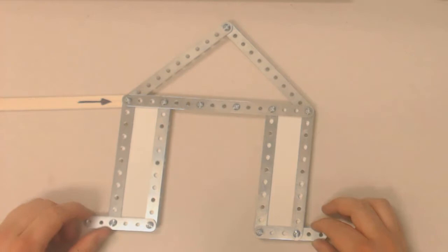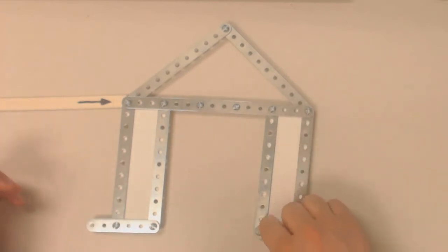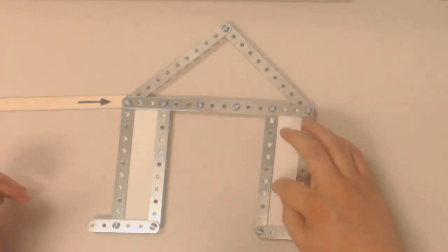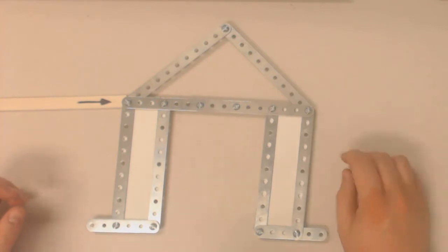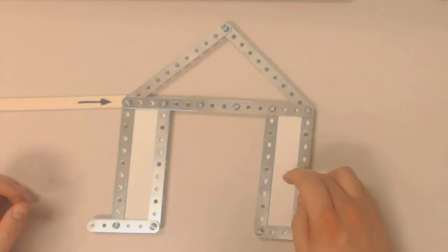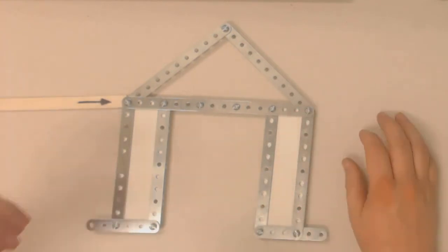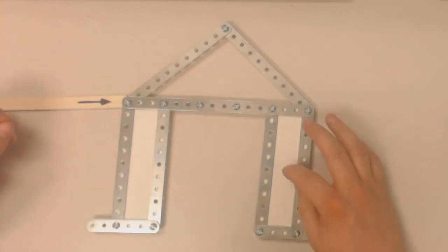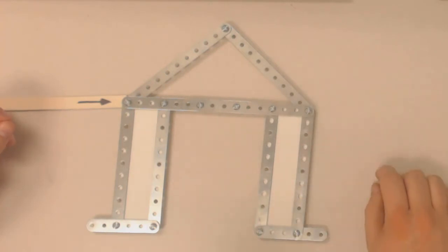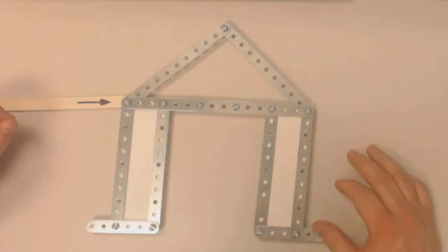towards the right. So in this sheet, which is commonly plywood, it gets loaded in multiple directions. Across this diagonal, this plywood is experiencing tension, but across this diagonal, the plywood is experiencing compression. And then at every other point within that plywood, it's either a combination of tension or compression, depending on where that point of the plywood is with respect to the geometry of the house and the direction the forces are being applied.